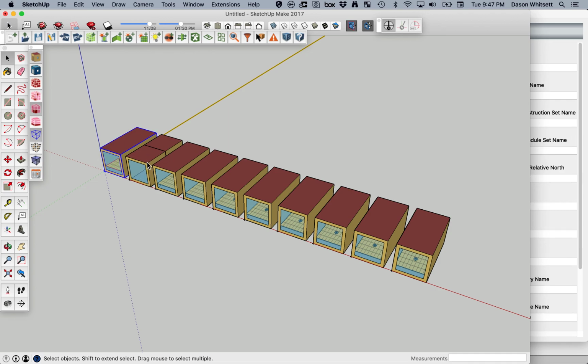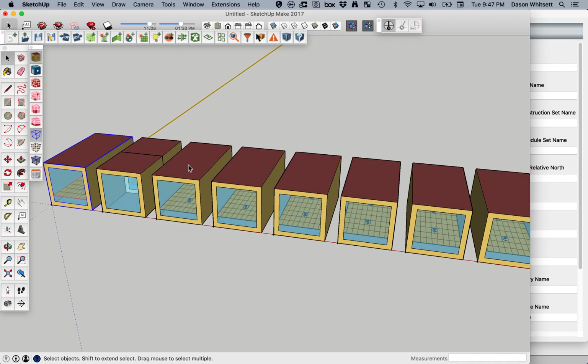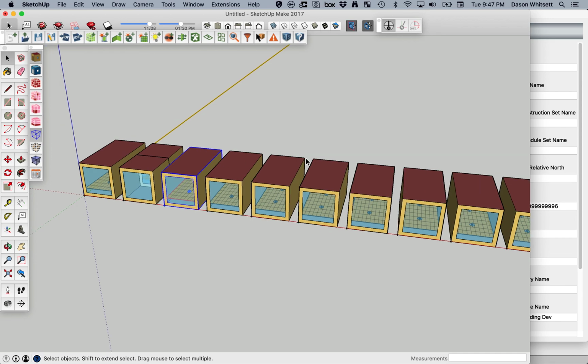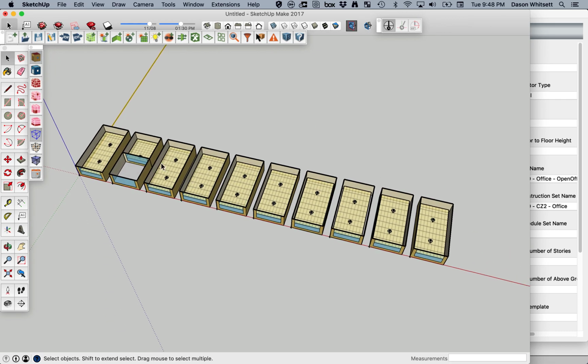We're not going to do anything to that. The next one, we're going to demonstrate how light can travel through a window, through another interior window, and into a second zone. And then we'll be looking at putting a basic shading device on this third space here, and then comparing some of the results. Each one of these spaces has an illuminance map and some daylighting controls in it that we'll be using to test some of our results here.